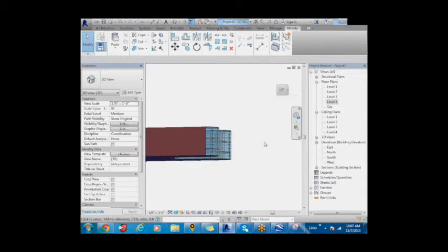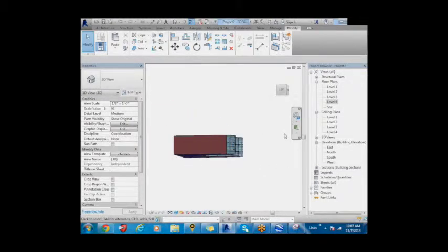So here we started off with the conceptual mask and then we added the walls and the roof and the floors. And then we resized the conceptual mask and we resized all our building elements as well. Now, Ladi would continue with grids and laying out beams and columns.